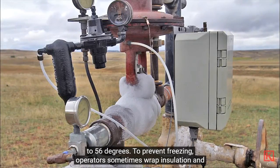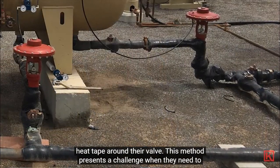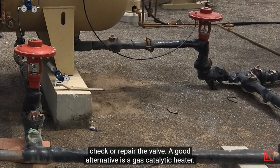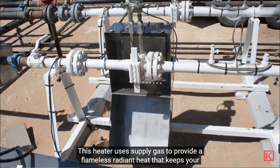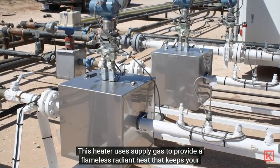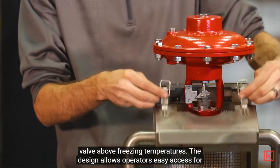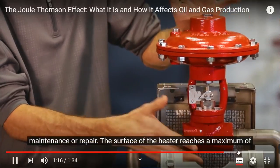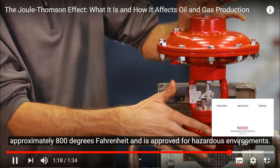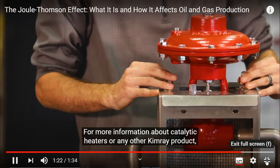To prevent freezing, operators sometimes wrap insulation and heat tape around their valve. This method presents a challenge when they need to check or repair the valve. A good alternative is a gas catalytic heater. This heater uses supply gas to provide a flameless, radiant heat that keeps your valve above freezing temperatures. The design allows operators easy access for maintenance or repair. The surface of the heater reaches a maximum of approximately 800 degrees Fahrenheit and is approved for hazardous environments.